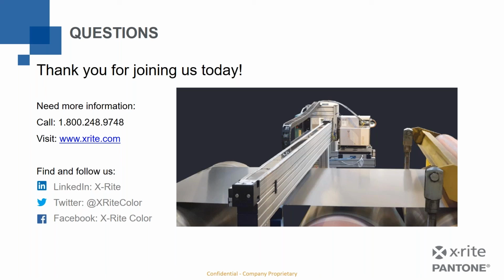Now, I say that with a caveat. You could force a problem if you wanted to, right? If you took some really high luminance beam of light and focused it right where you're going to take your color measurement, it might have an impact on your color measurement. But for the most part, extraneous light doesn't have an issue, and in fact is something that's really well controlled by the means by which we both illuminate and measure these samples.